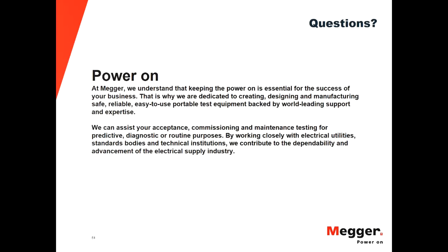The other reason that the test is considered destructive is if you go below the minimum voltage or the end voltage specified by the manufacturer, then the chemistry is going to be affected, and in that case, you are definitely going to affect the ability of the battery to hold energy. So you're affecting the capacity. But as I mentioned during the presentation, if you handle the test properly and do things in the correct way, you're not going to be affecting the battery. So that is very important.